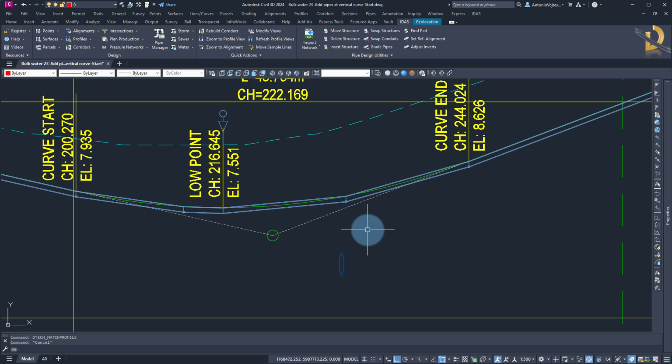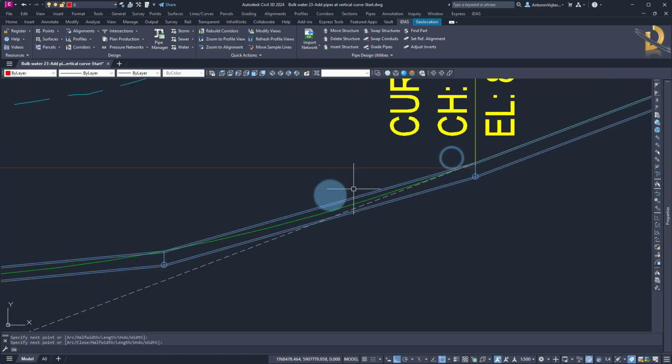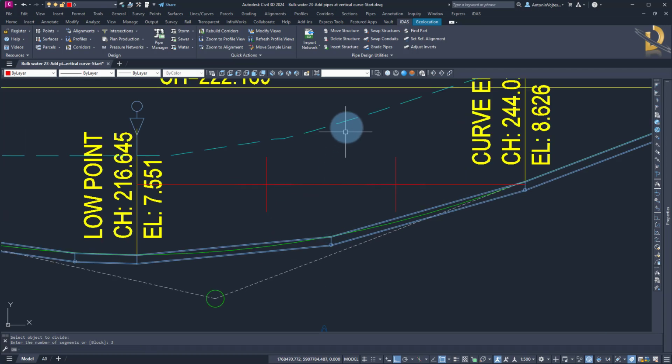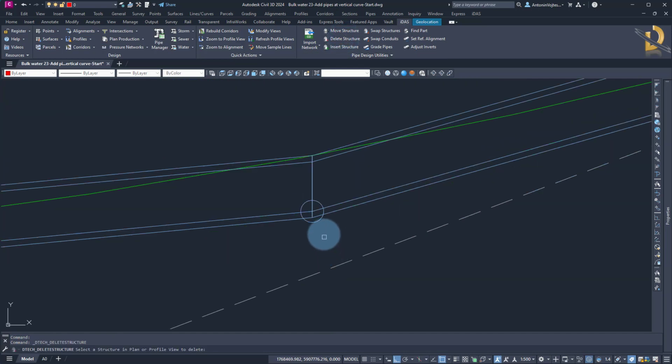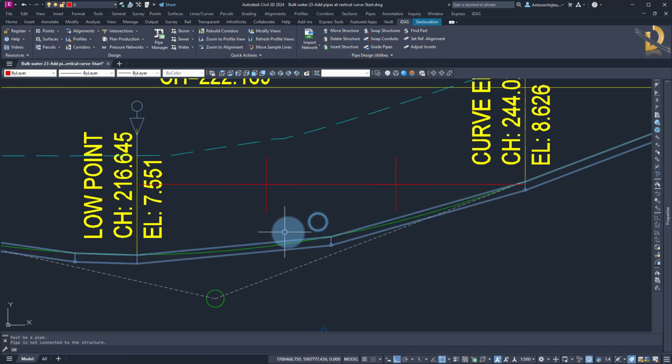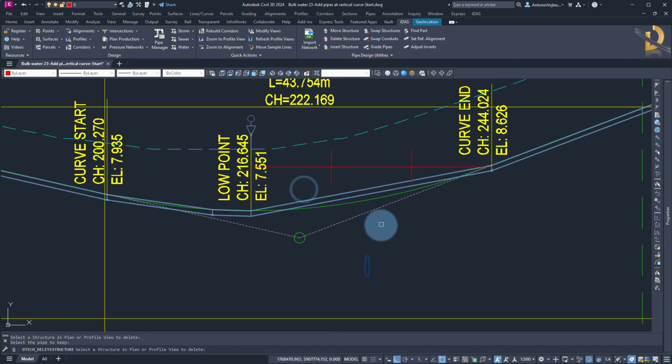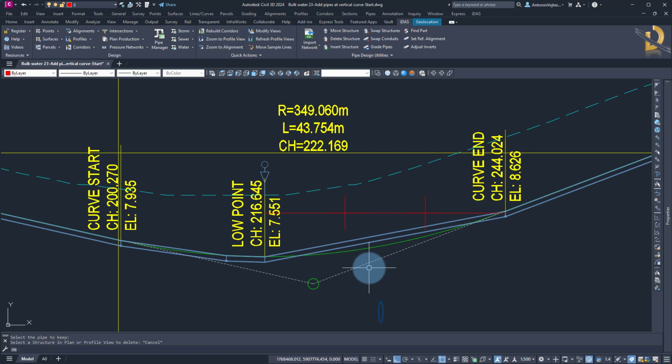Of course, you can do the same approach for thirds, because you can always draw a line from here to there, and I can use a command divide. Let me do it again, divide, then I select the object, I use a 3, and I can insert structures at those points. I can quickly do it. I can delete this structure because this is something I don't want. Now let me do it again. I didn't select the correct outgoing pipe. That's correct, the remaining pipe actually.